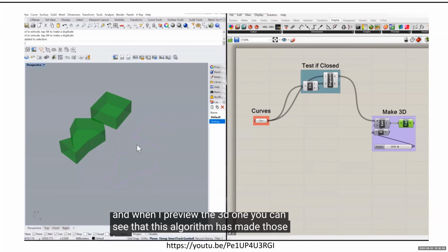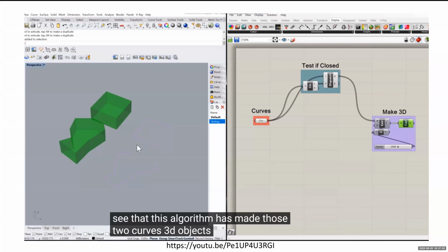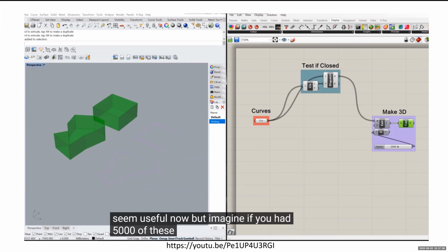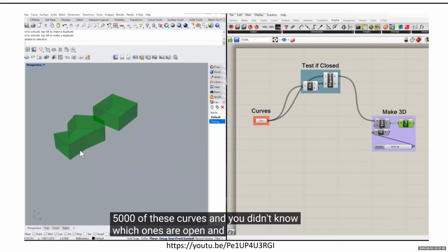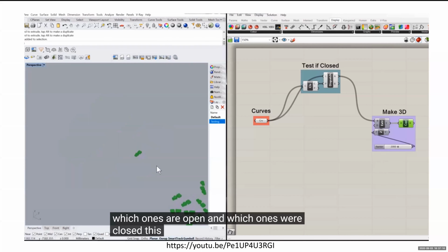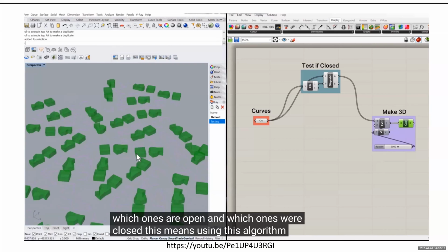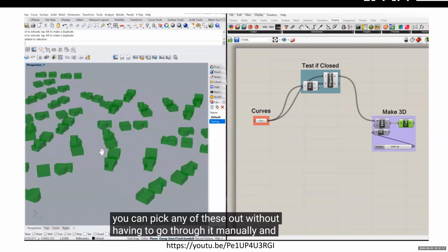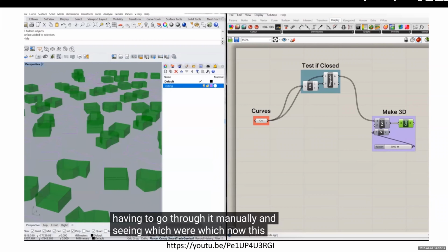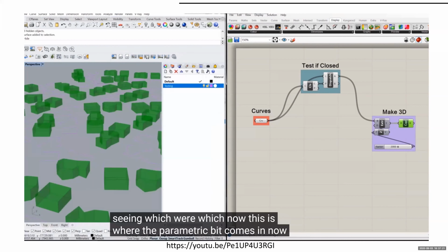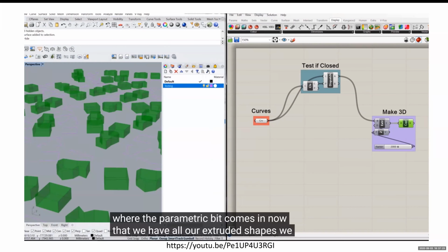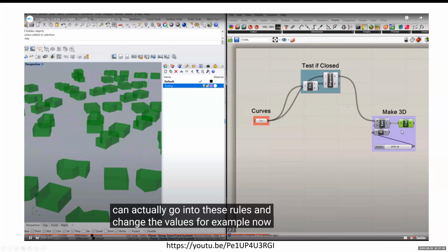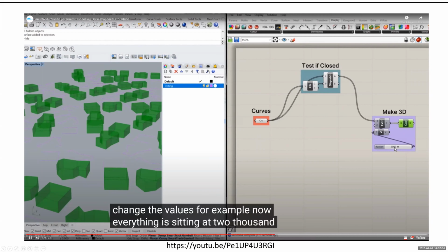For example, a case for parametric modeling is the number of chairs depends on the size of the room, right? So if you know the formula, then you just create the two boxes. One is the size of the room, the other one is the number of chairs, and you define the formula in the middle. Now, in your design, if you just change the size of the room, you do not need to manually change the number of chairs, because this interactive window will basically change the number of chairs automatically. Make sense, guys?